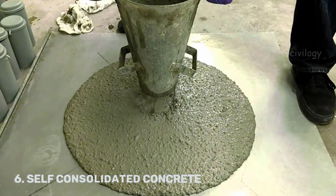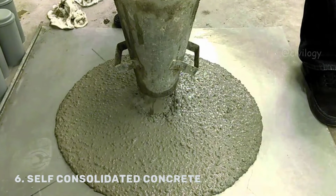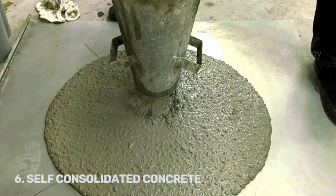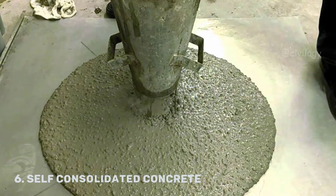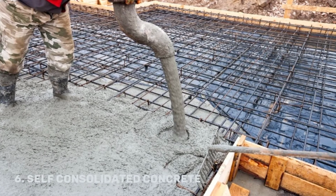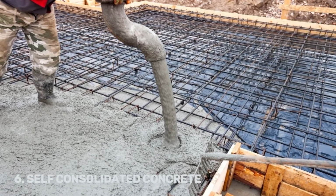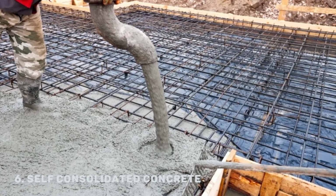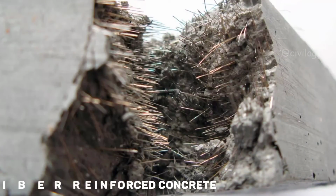Next, self-consolidated concrete. These types of concrete are compacted by their own weight by means of the consolidation process. There is no need for using a vibrator or doing manual compaction, which is tedious nowadays. The workability of concrete is always high in this type of concrete. That is the reason it is known as flowing concrete. But the cost of the concrete may be higher than the normal concrete, but it is worth using for the larger constructions.